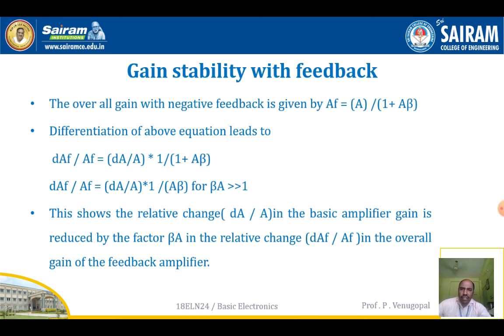This shows that the relative change dA by A in the basic amplifier gain is reduced by the factor A into beta in the relative change dAF by AF in the overall gain of the feedback amplifier.